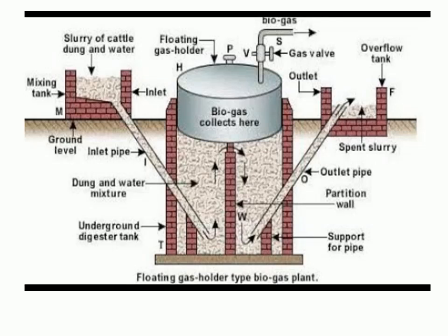Then how does it work? First, the mixing tank. From the mixing tank, the slurry is obtained. That means biomass is mixed. Biomass may be agriculture waste, industrial waste, or municipal waste. This is mixed with water, then a liquid formation is obtained. This is referred to as slurry. This slurry is fed to the digester through the inlet tank. Then the initial action takes place, that is acid formation. Hence anaerobic action, fermentation, takes place.